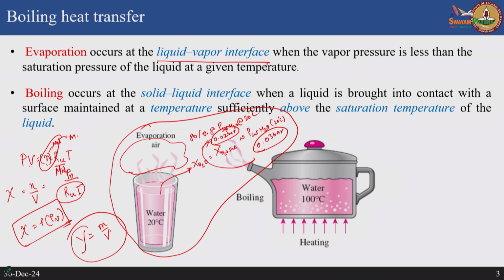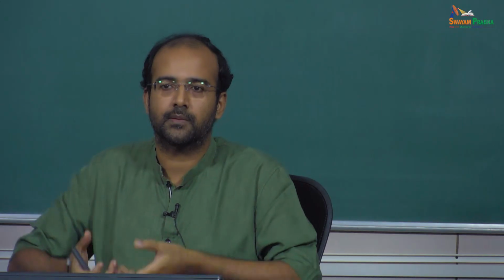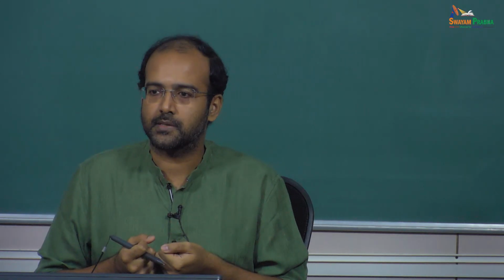That is due to evaporation, and the cooling that it produces is called evaporative cooling. Evaporation is not just mass transfer, where molecules convert from a liquid state to a vapor state. Associated with that, energy is taken away from the liquid in order to become vapor. It takes the latent heat of vaporization as the energy required, because you need to supply energy to convert a liquid molecule to a gas molecule, and that energy comes from the bulk of the liquid, and in the process the temperature of the liquid also reduces. So, this is called evaporative cooling.